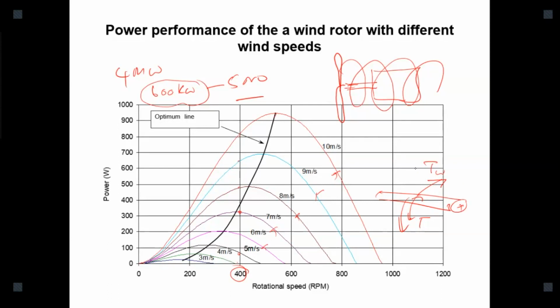Then we are considering V1 and V2. V2 is the linear motion. In all that previous theory, we considered only the horizontal component. But there is some energy in the wake also. This is a loss here, because the difference between input and output energy is converted to mechanical energy. We did not account for the wake, that means the rotational part. Actually we are calling that the wake.